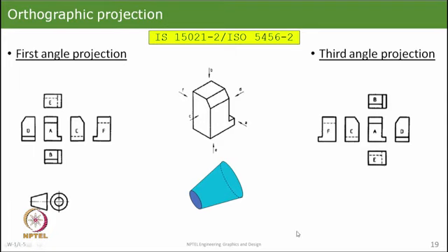What you see from the right is what you draw on the left. What you saw from the right was that the larger diameter is here, the smaller diameter is here, and it looks like a cone. This symbol is the international symbol which tells you that the drawing is in first angle projection. Nobody will write first angle projection, they will only make this sketch, and it means this is how the views have been placed.